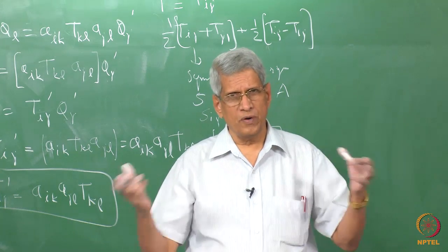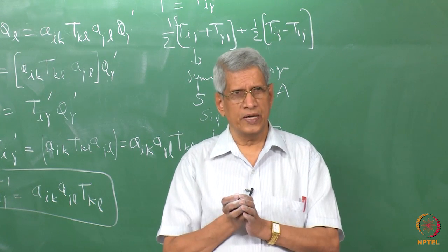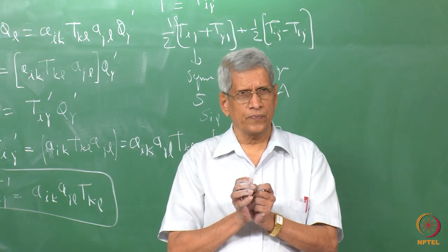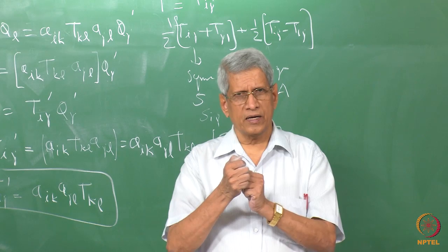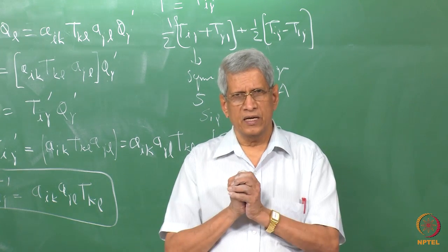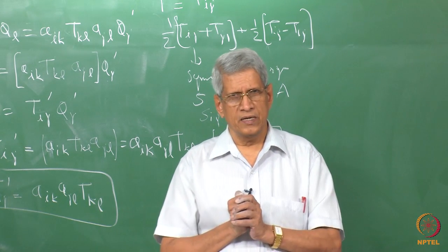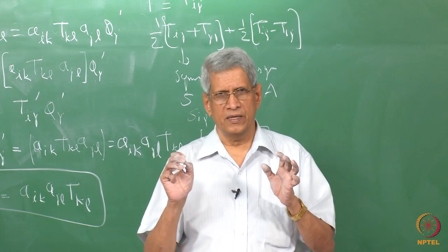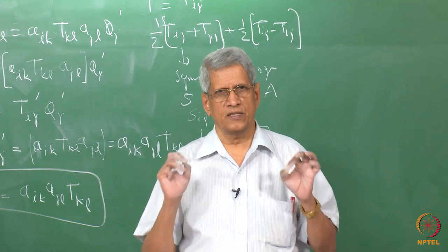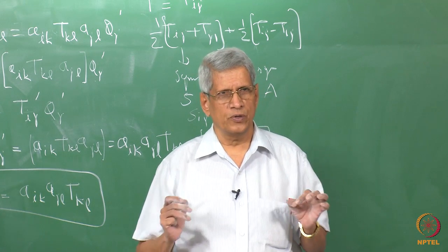When we say in terms of a principal component, what we mean is that by applying only the dilatational, that is either a compression or extension along some directions, the same volume and shape change could be obtained without involving a shear strain itself.